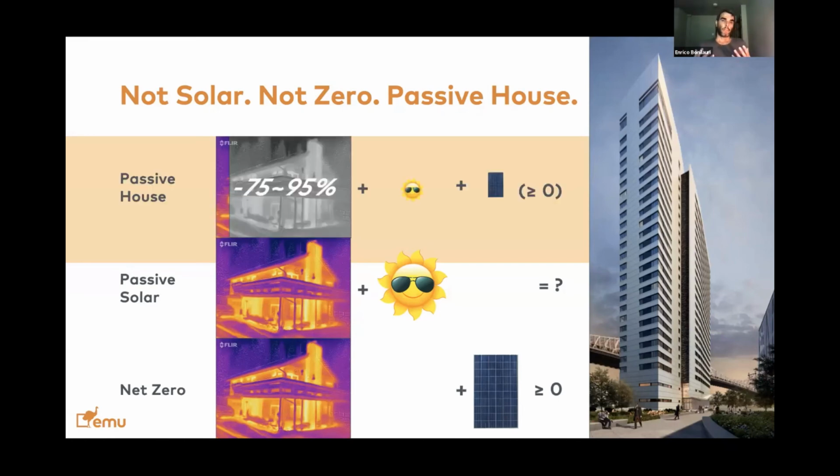So the whole concept of Passive House is that we improve the building envelope considerably so that the need for heating and cooling is reduced by about 80 to 90% compared to existing buildings, and even 80% compared to buildings that are built meeting the 2018 Energy Code. Keep in mind that in construction, 2018 is the future. It's 2020, but for construction, 2020 is the future, in that the 2018 building code is still not widely adopted in most locations in the US.